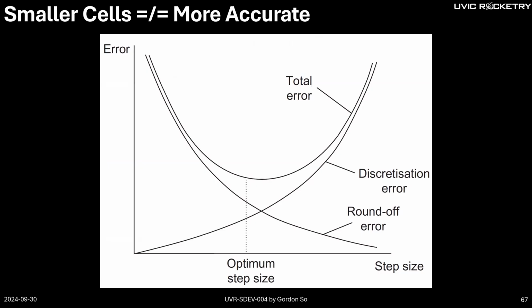And then, of course, you deal with your discretization error, which is how close your mesh is to the actual surface you're trying to capture. So you're fighting two things at the same time, and there will be a sweet spot. You don't really know that sweet spot, but it's just something that you need to try.